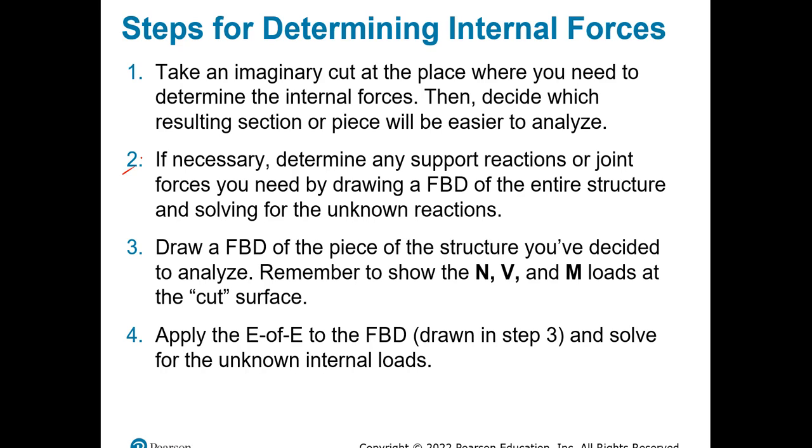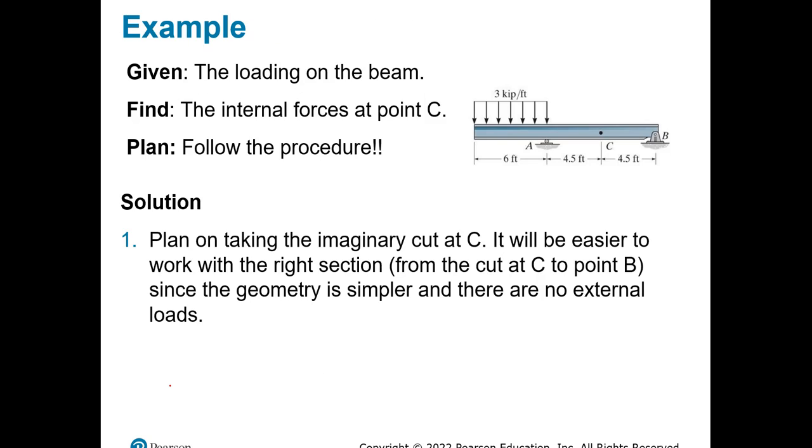After that is calculated, we need to draw a free body diagram of the piece of the structure that you've decided to analyze, and remember that you need to show the internal loads. And then after that, all you have to do is apply the equations of equilibrium in order to solve for the unknowns. Okay, sum of forces in the y, sum of forces in the x, and sum of moments. And as always, we're going to have an example.